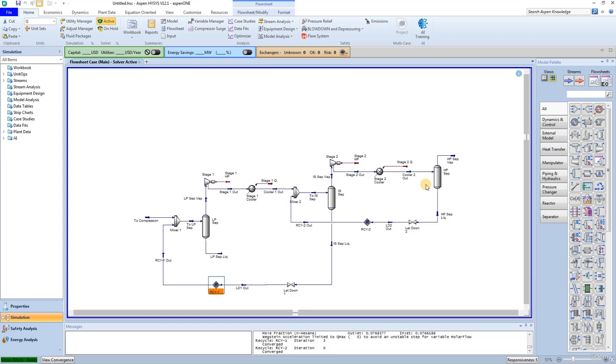Add the compressor curves. Compressor performance curves allow you to calculate hydraulic head and efficiency as a function of flow ratio into the compressor. Using compressor curves in your Aspen HYSYS simulation allows you to model existing or potential plant equipment. In this task, you will investigate a set of compressor curves which have varying operating speed, allowing the compressor to change its speed to meet demand. You will install these curves into the stage 2 compressor.